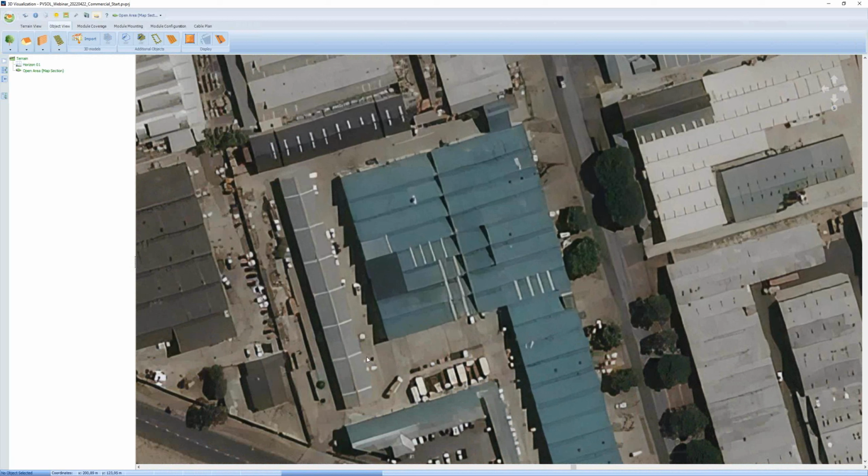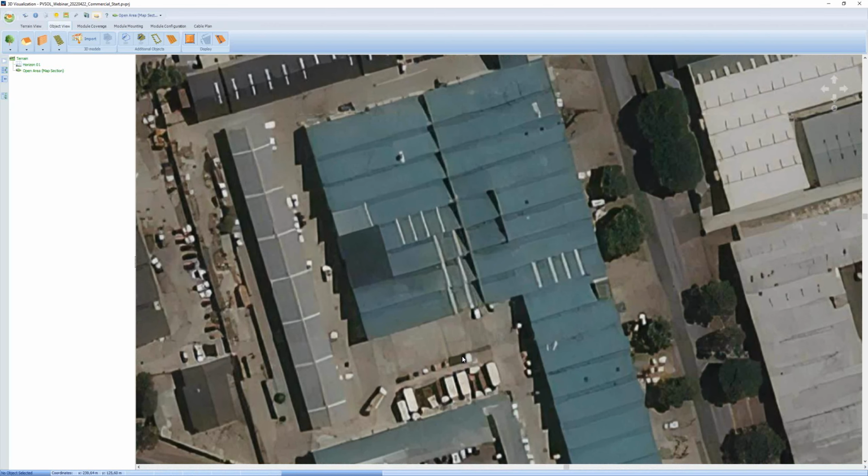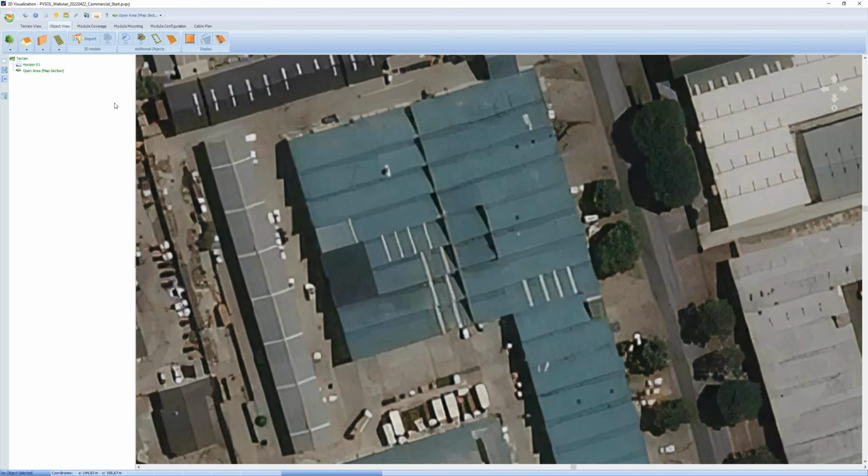Of course, now we would have different options. As Thomas mentioned, it looks like there are different buildings with pitched roofs, so we could use different pitched roof buildings and define them one by one, or we could use the full building here and add sheds to it, etc. Those are the options we have, and we have decided that we first draw the outlines of the whole building.